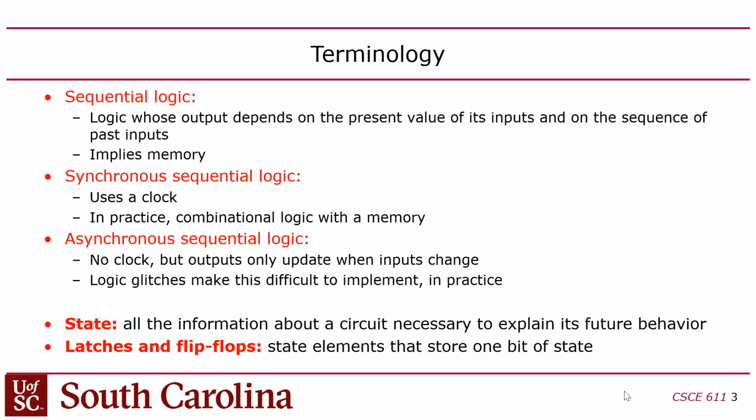That's when you have logic that's cross-coupled, where you have outputs of gates feeding back into the inputs, but it's designed in such a way that the circuit is stable, in the sense that the state of the circuit would change only when an input changes. So in other words, the state would change whenever one of the inputs changes. And in fact, there are some examples of this.